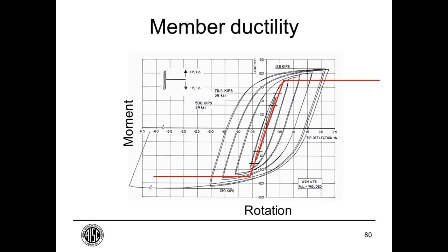That area under the graph is hysteretic energy that's been dissipated, that has actually gone into heat that you can feel in the steel. Each of these cycles has an area to it, and that is energy that is dissipated. That is earthquake energy that is absorbed by the system and not returned like a spring returning the energy to vibrate the system more.